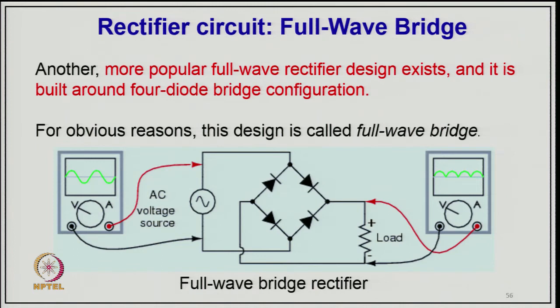this manner. Here you can consider that you are not using the transformer, that is the benefit, but the limitation is you are not providing the isolation, and you can't change the voltage level. Whatever voltage you are getting from input you get rectified in the output.